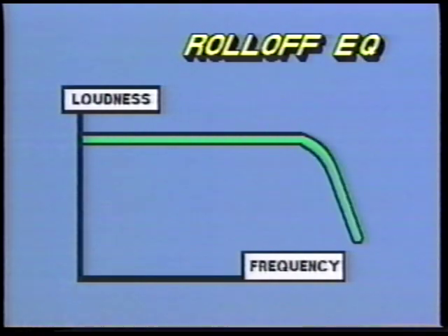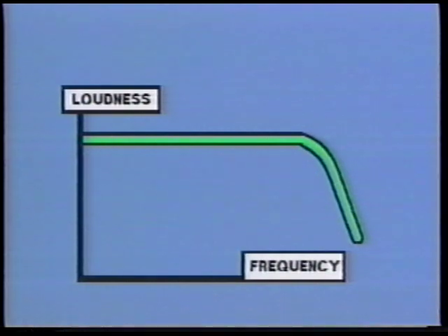There are several different types of equalizers, and they are described in terms of their EQ curves. An EQ curve describes the frequency versus loudness pattern of a particular equalizer. EQ curves fall into a few basic groups. Roll-off filters reduce the amplitude of all sounds beyond a selectable frequency point. The amount of reduction increases linearly beyond that point. Low-frequency and high-frequency cut filters, like rumble or hiss filters, usually operate with a roll-off curve.